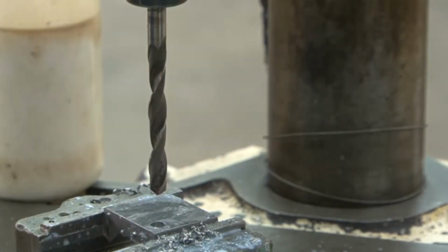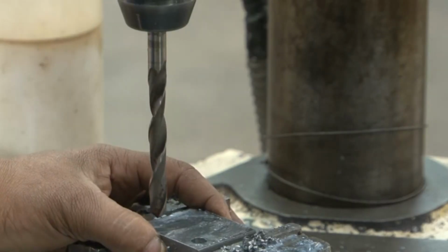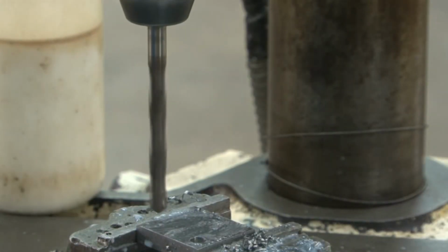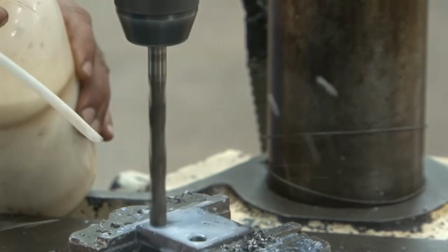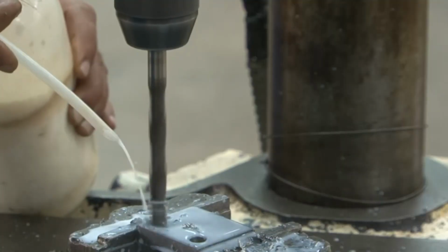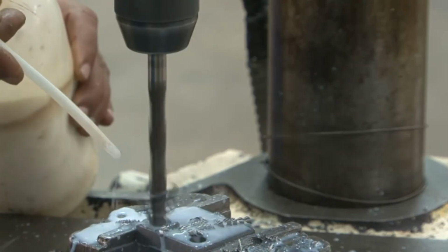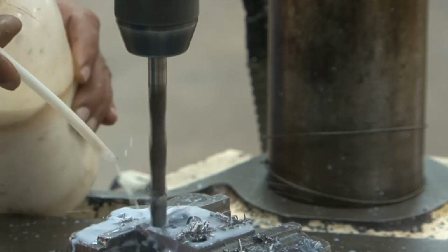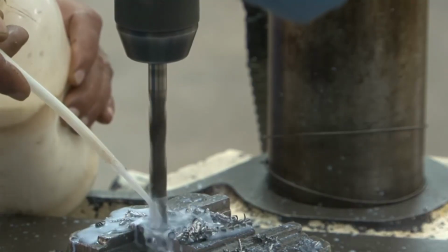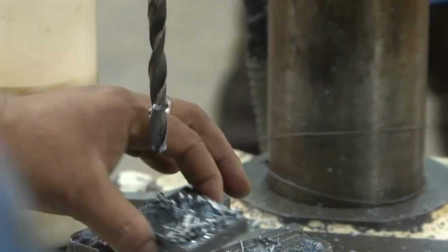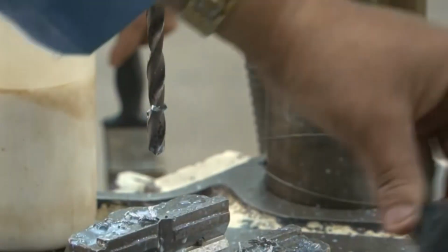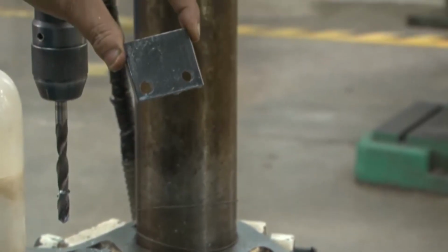Oh, this is 9.8 millimeter diameter drill. So, that is for the other hole. With the same speed, the other hole is being drilled. The cutting fluid has to be provided, because there will be a lot of friction and a lot of heat generated. Otherwise the drill will be worn out very fast, and the accuracy of the hole drilled will be less, because of the high friction between the drill and the hole that is being drilled. So, now both the holes have been made, and as you can see they are of different diameters, because drills of different diameters have been selected. Okay.